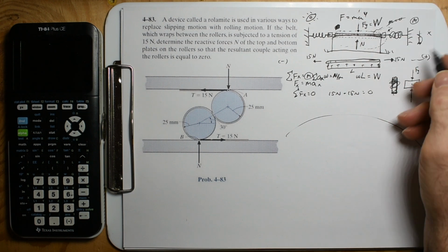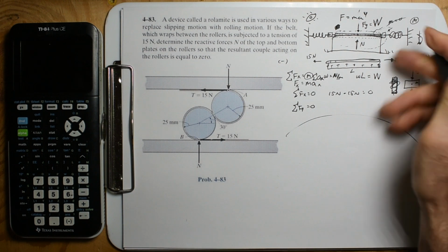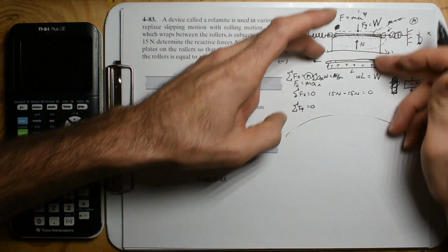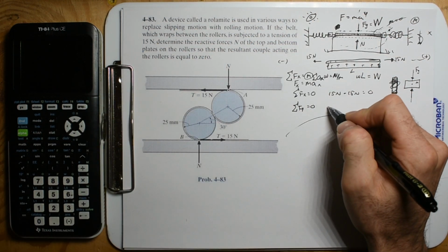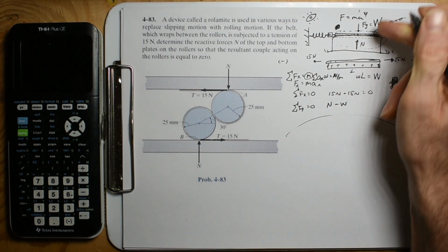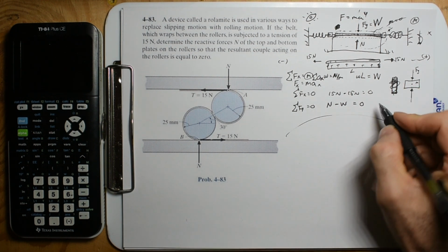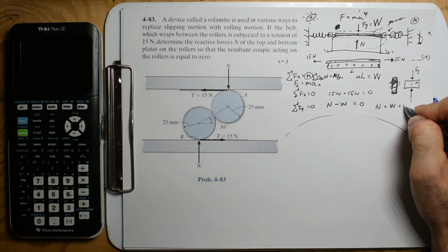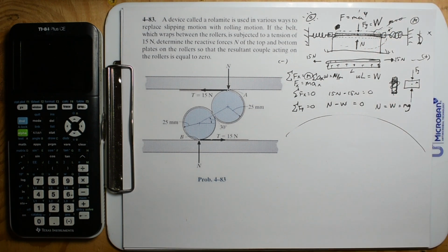Cool. And then in the y, it's the same thing. We're going to have the sum of the forces in the y equal to 0, because by observation, this thing is not moving. It has 0 velocity downward, or in this direction. And so we would say the normal force up is positive, minus the weight down, negative. That's going to equal 0. So from this equation, the normal force is equal to the weight, and so the normal force is equal to the mass of the rope times gravity.